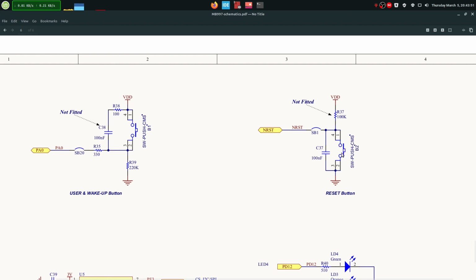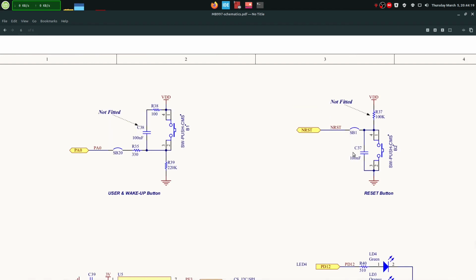So this button is reset, enabled when pressed. High is the state of the button, so high is, let's say, closed. So when you close the button, the reset kicks in, and the processor doesn't work at that point. So you could call it active low. When you release it, the reset is disabled. So the pin goes to low when you have the button at 1. If that was confusing, the next button is right the opposite, so you might draw a conclusion from that.